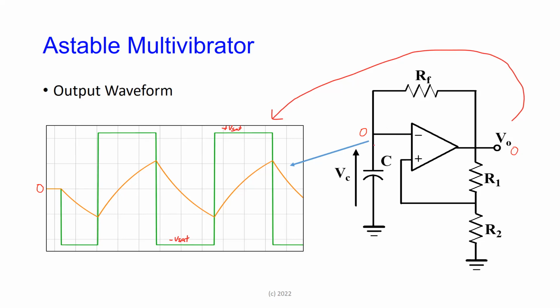And what's going to happen is that the capacitor voltage is not going to remain at 0 for any length of time. It's going to try to increase very slightly because there's leakage current floating around in the circuit. Microamperes, picoamperes, it's very small, but it is there just because the circuit has to operate.